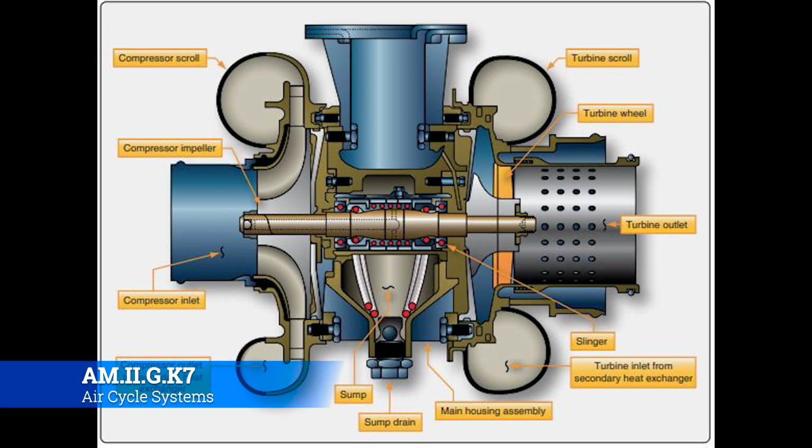The steep blade pitch of the ACM turbine extracts more energy from the air as it passes through and drives the turbine. Once through, the air is allowed to expand at the ACM outlet, cooling even further. The combined energy loss from the air driving the turbine, then expanding at the turbine outlet, lowers the system air temperature to near freezing, which is then remixed with bleed air to bring it back up to 70 degrees or whatnot that's actually tolerable to the passengers.